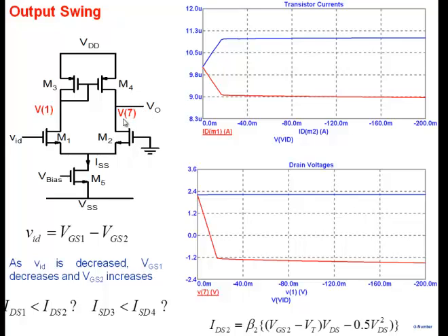This voltage is becoming lower, and the effective drain to source voltage becomes lower here, and that counteracts the increase in VGS. So VGS becomes larger, VDS becomes small, maintaining almost the same current here, right? So M2 goes into linear region. And as M2 goes into linear region, what will happen to the drop VDS here? VDS becomes small. How small can it become?